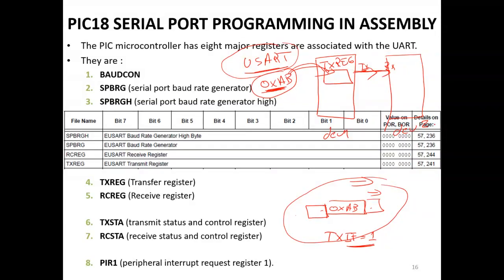So device number 2, if it is a microcontroller, will receive the data serially. The data will be deframed to remove the start bit and the stop bit, and the data will be here in the RC register. And then the user has to just read the data from the RC register.